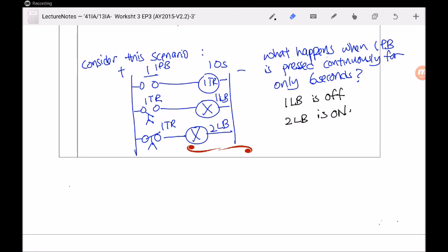With this, we have covered EP3, in which we learned about the input elements like the different types of sensors: inductive, capacitive, and the different types of photoelectric sensors like through-beam, retroreflective, diffuse reflective, and so on and so forth. And in the last two examples, you learned about signal processing elements, for instance the control relay and the time delay relay, which we will use extensively later on in EP4.